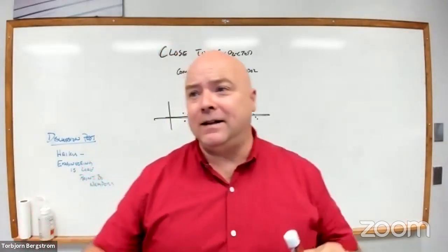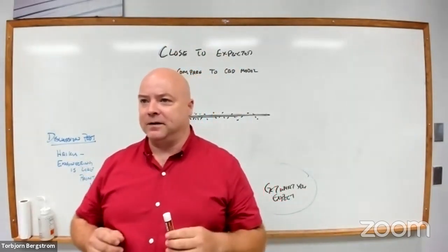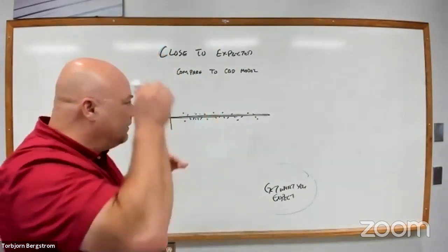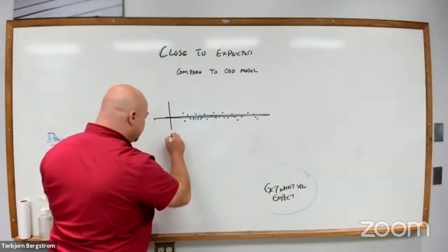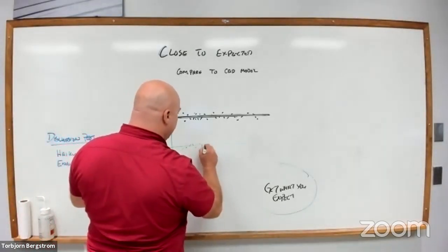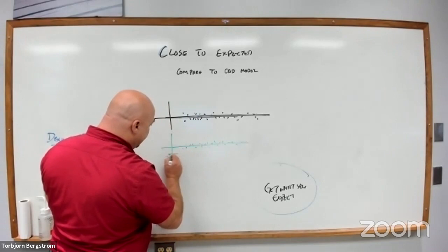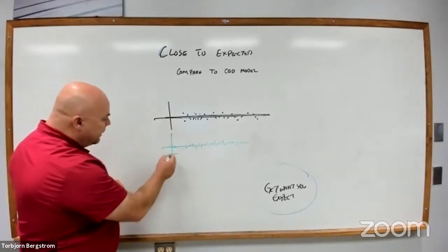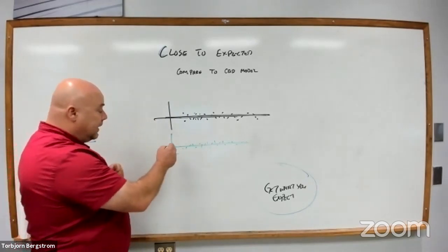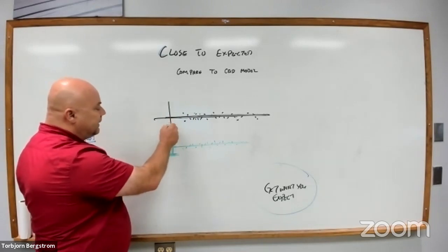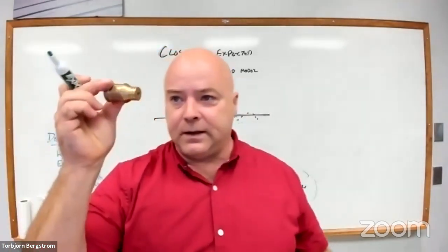And the people that certified it, they measured it by bouncing light waves off of stuff and knowing what the speed of light was. So I can measure my measurement standard and see if I get the same kind of variation, the same kind of standard deviation. And I know that the true value is here and my measured value is here. I know that I have a linear offset between my measurement tool and the true value. So I can apply that linear offset here, and I could then know what the true dimension of this is,